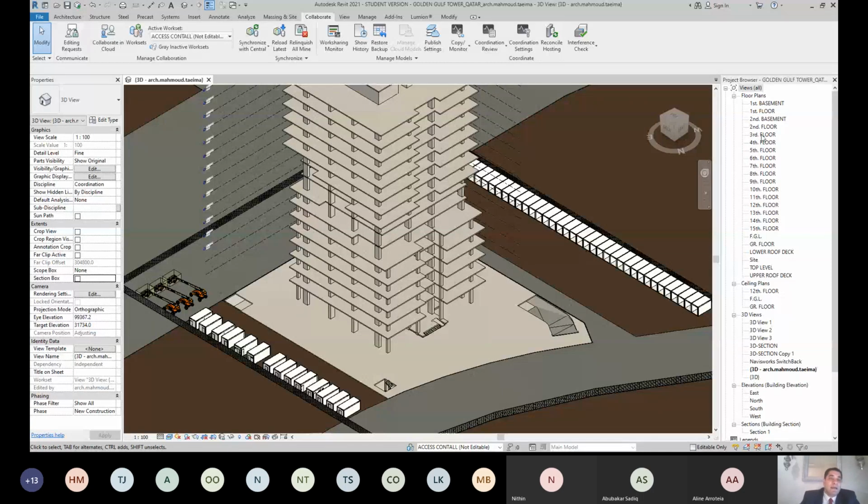Okay, and after that we get from Primavera the start for every activity. We have the start time and the end time for every activity. Now we have everything to make the 4D simulation. Combine the time schedule with the activity, and I will share it. We will see it in the model now.